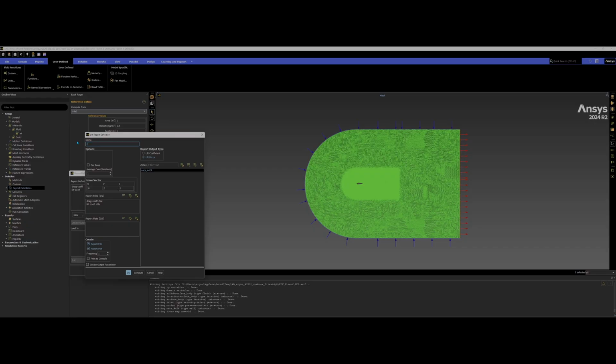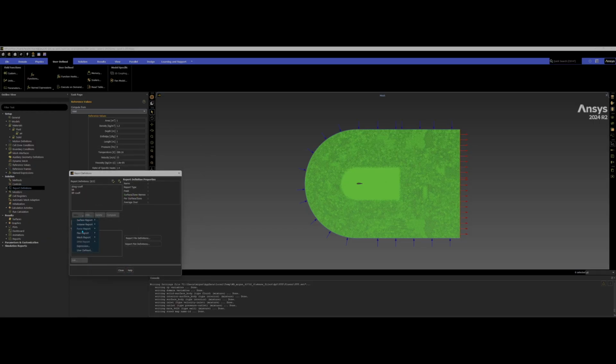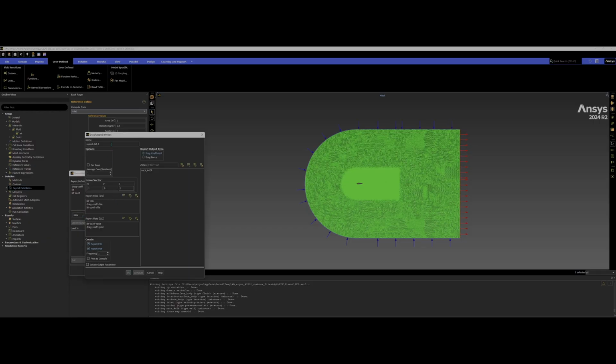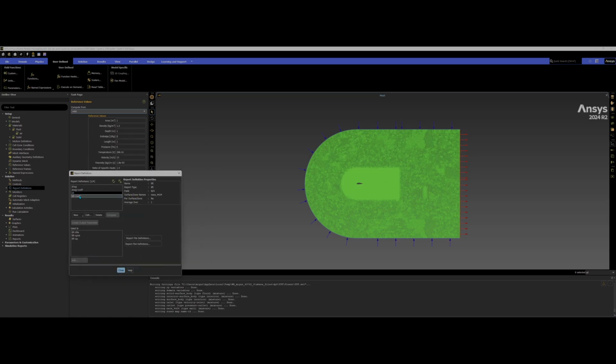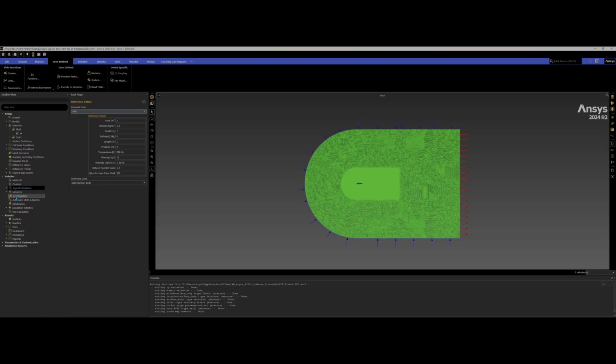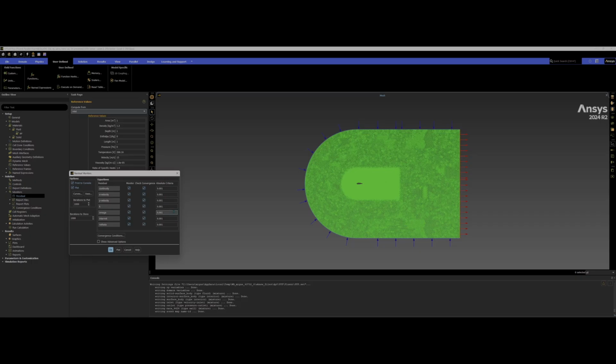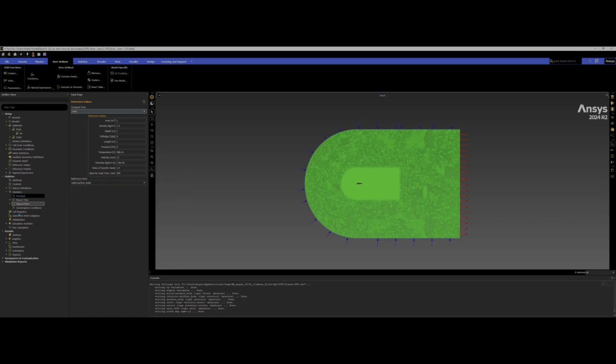So now I'll just do lift here. Here you go. And drag. Drag force. Print to console. Good. There you go, this all looks great. Okay, close it. Now, monitors, I'll leave this default because we're going to be running many simulations, so this will run quicker. I'll leave it like that, but if you wanted more detail, you could mess with that.